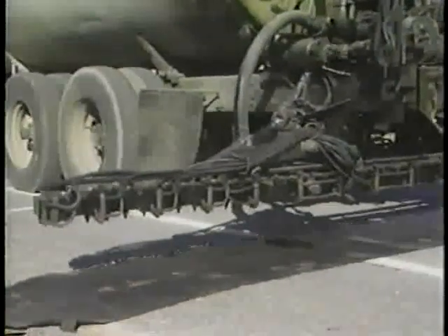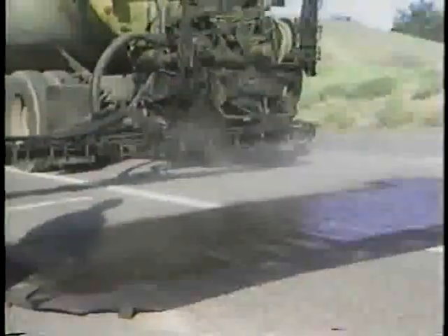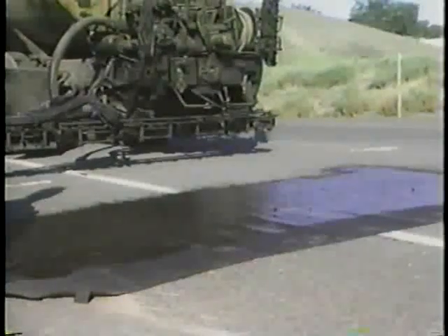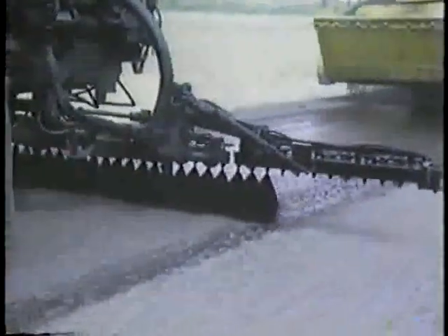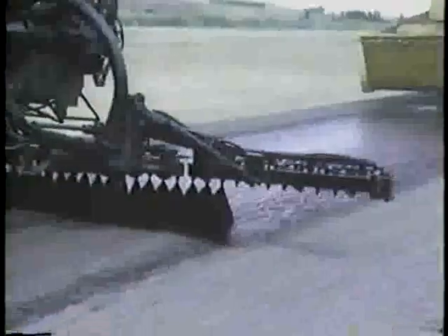and uniformly angled, usually 15 to 30 degrees in relation to the spray bar. If the nozzles aren't angled properly, the spray fans will hit each other and produce an uneven coverage. It's a good idea to check the spray both before the actual application and soon after startup, so that any problems can be corrected before the operation moves too far. Spray bar height also affects proper coverage. By adjusting both the bar height and the nozzles, different spray patterns can be made as shown here. Usually a double or triple lap is used for seal coats.